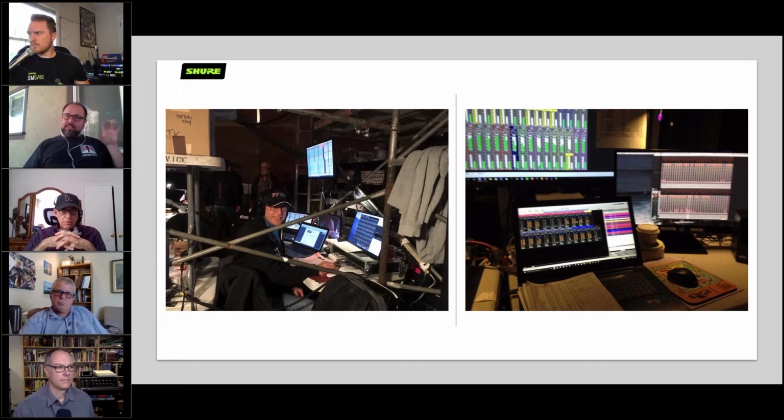The A2s like to be able to physically look over and see the rack, but as time goes by and they're more familiar with the software and using Wireless Workbench, the better. One thing I do suggest is putting it in monitor only. A lot of times, if you have a touch screen and you actually point at the RF that you're using, you can mute it.